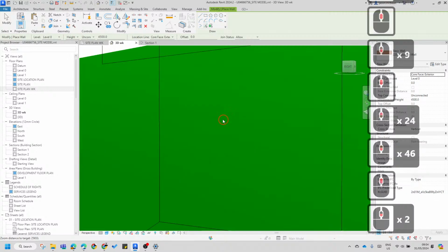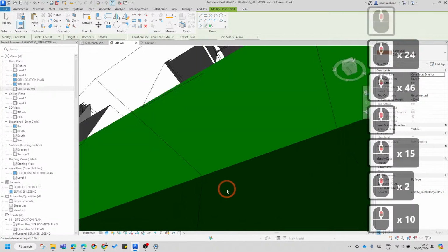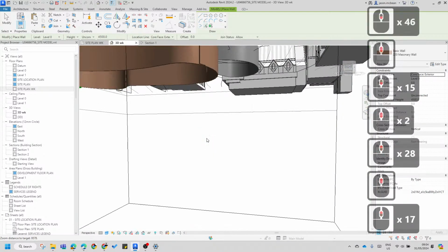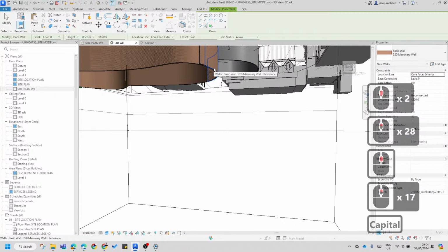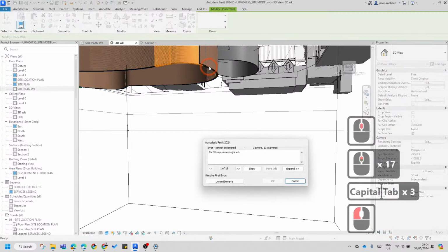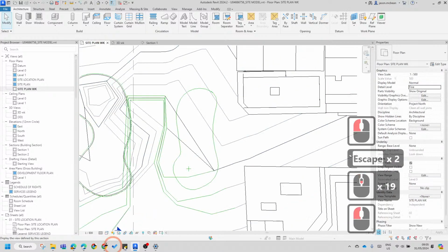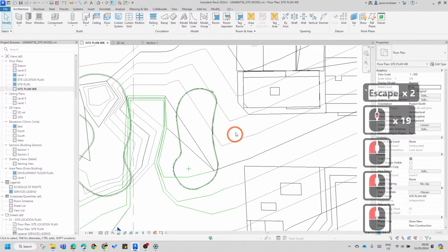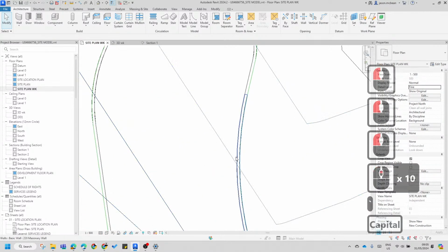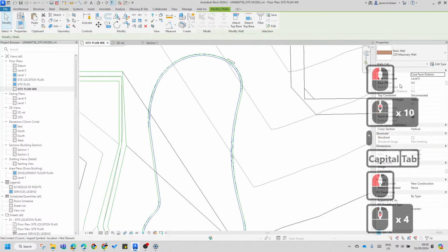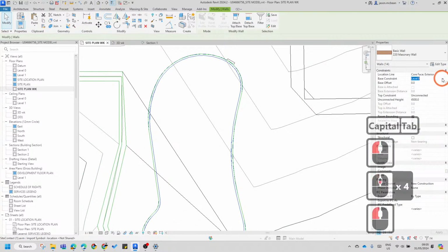So, sorry, let's get underneath here. Get into the top of solid. Okay, select those. Tab. These walls started off the wrong level. Let me just go back to start working. Now I'm going to switch this to hidden. I'm going to tab these walls. So tab. These walls started at level, see that was wrong, it should have been datum.